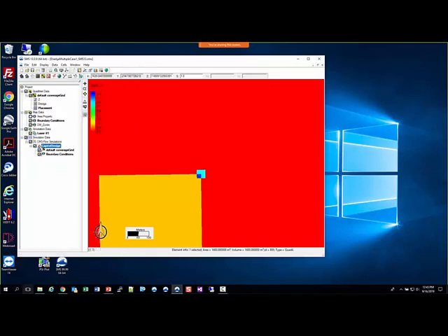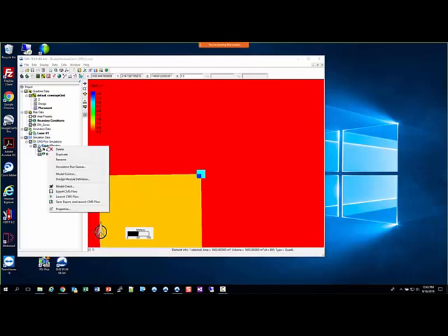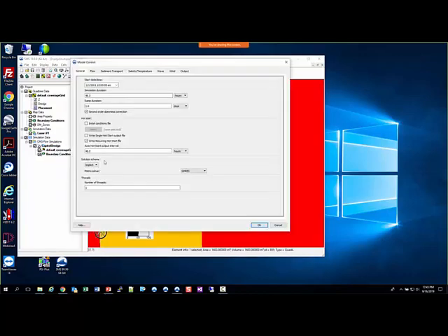So for this case, we need to go ahead and set up the rest of our model control. So right-click on the simulation again and go into model control. And we're going to enter the values as we kind of mentioned in the presentation. So our start date and time, you would modify that. For us, our simulation duration is going to be 550 hours. And we specified ramp duration of 2 days. These are totally up to you.